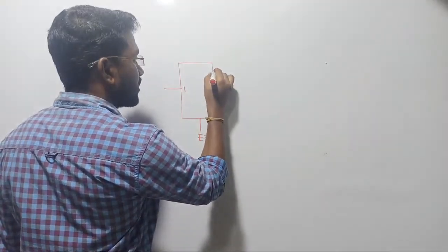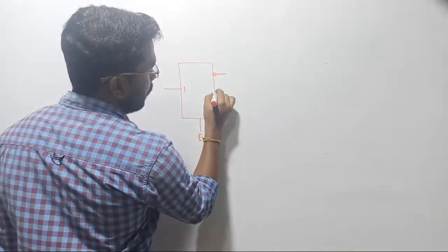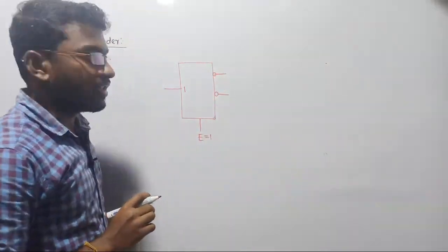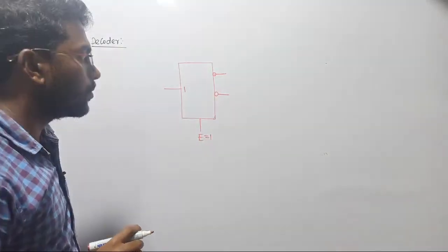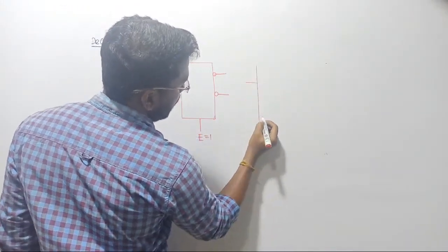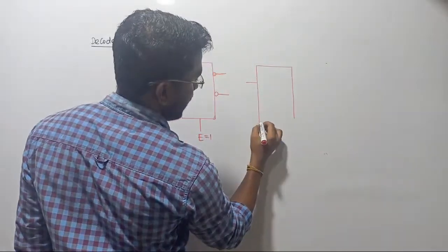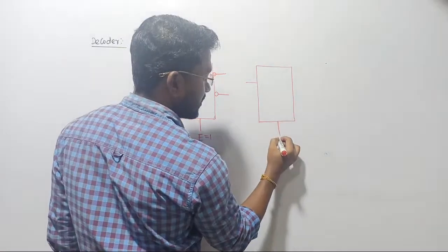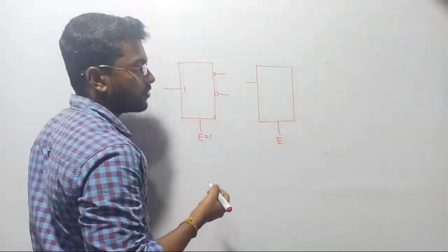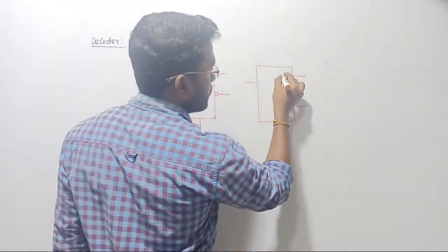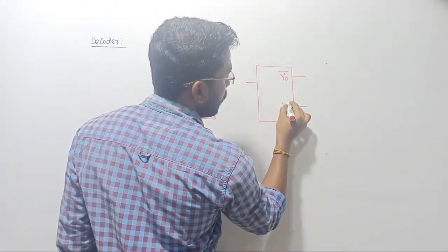See, on the output side, you can see this type of output now. If I find this type of output, what is the difference between the previous one and the present one? See there, once again, there is a bubble. So in the output side, people are using two types of representation. Either you can find the bubble, or, since we are using an active enable pin only, in the output side they take the line outputs directly like this, but they will put y0 bar and y1 bar.